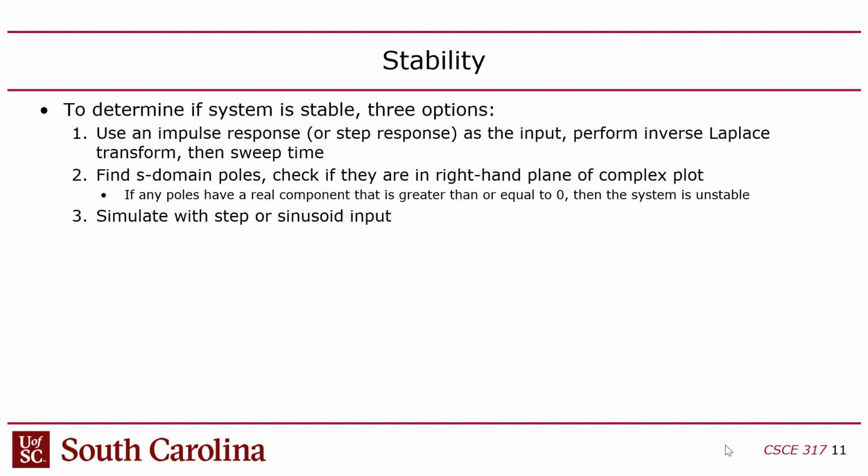But the other nice thing about that is mathematically, the impulse in the S domain is a 1, literally just the number 1. And so, as I mentioned, if you have an LTI feeding another LTI, you can multiply them together. Well, if the first LTI that's feeding the second one is a delta, an impulse, then that LTI transfer function is just 1. So you just multiply 1 times the second.